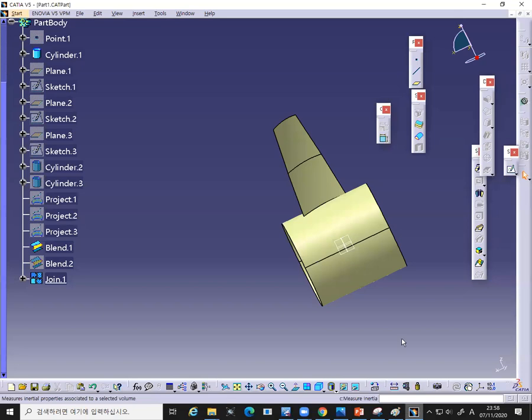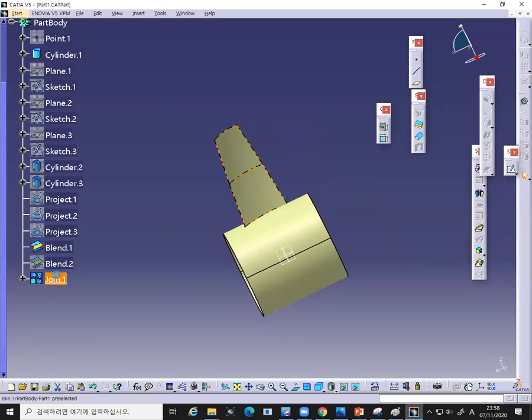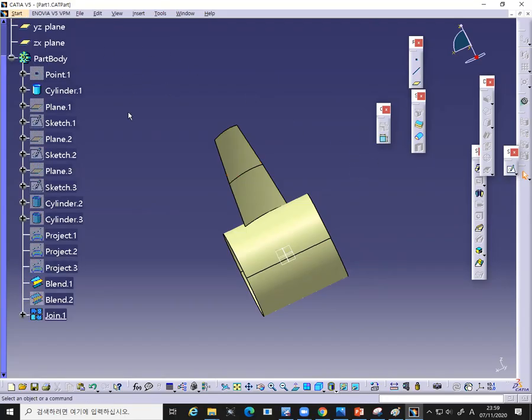Now after making this one, after join, suppose I don't use generative shape design to create the fillet. No split and no extract, no tools, just a thick surface, and give the edge fillet directly in Part Design. Let's see what happens when we do that in Part Design.